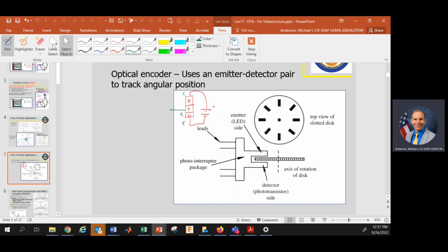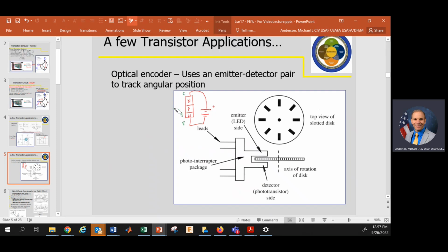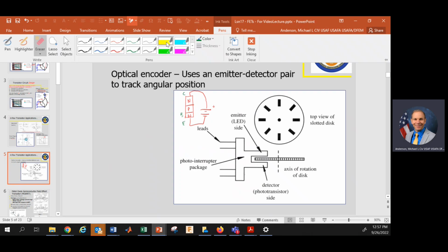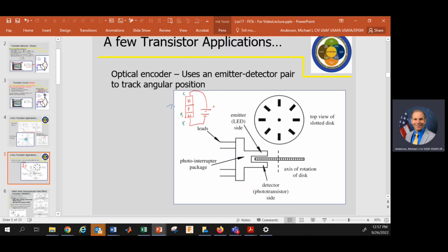But in the case of a phototransistor, it's actually light from the sun that falls on the base, and that's what forward biases the transistor and allows it to operate. I said from the sun, but it can be any light. Light, which is basically photons, falls on the semiconducting material, and that's enough to forward bias it and get it to operate.